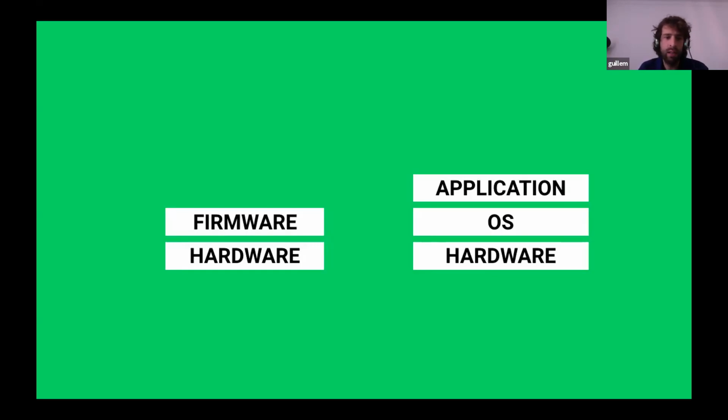But at the same time it does so, it means that someone could hack into your operating system and actually change the firmware of the code running your webcam. And for example, there was a case, as many, where they managed to turn the webcam on and off without turning the LED near the webcam on and off. So they basically succeeded in hacking into a laptop and reflashing the microcontroller running the webcam, and basically removed the line that was saying digital write high to the LED when the webcam is started.